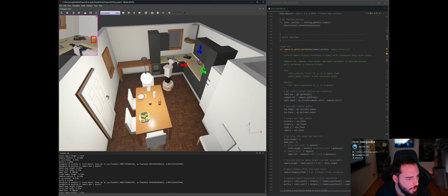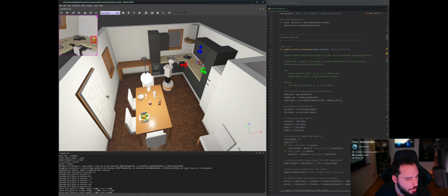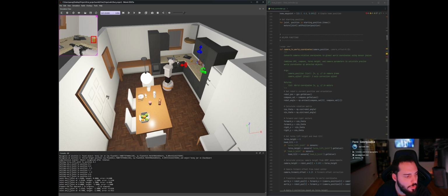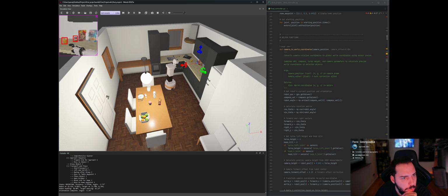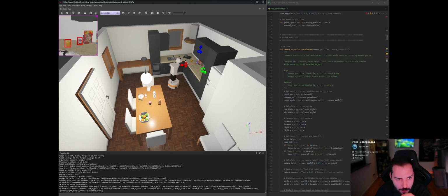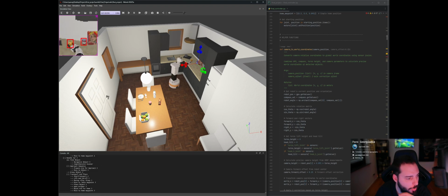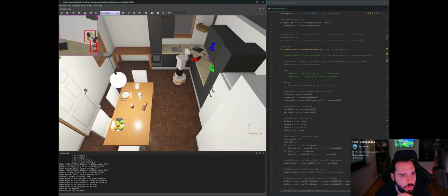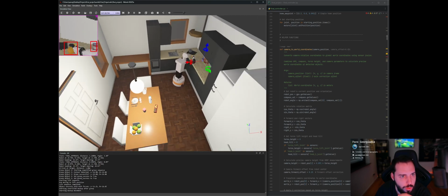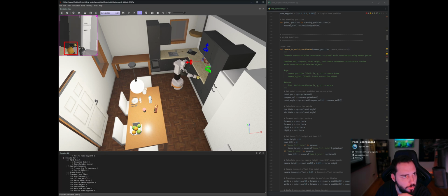Camera sees one object, it gets its location, puts that stored target position on the blackboard to be used, and then starts going into the move to arm position to start to calculate the inverse kinematics once it gets 1.23 meters, 1.28 meters close. Same thing, we have a success for calculating. It's then going to do a final approach movement very slowly, grasps the jar, lift and verify, back up, move to the table.